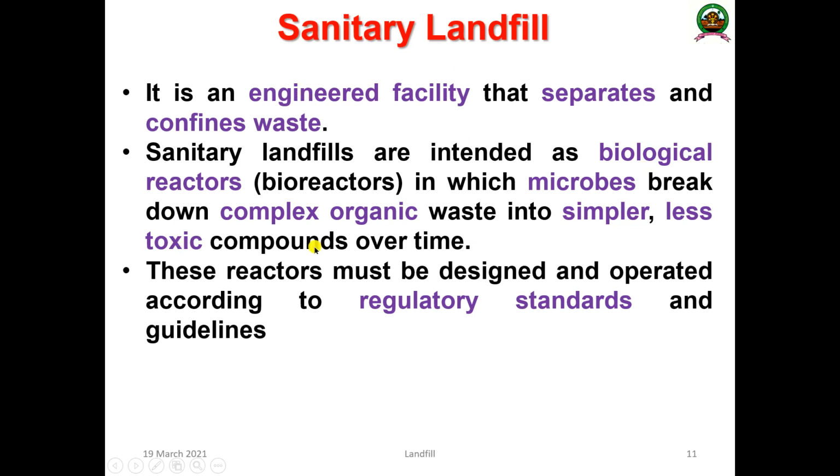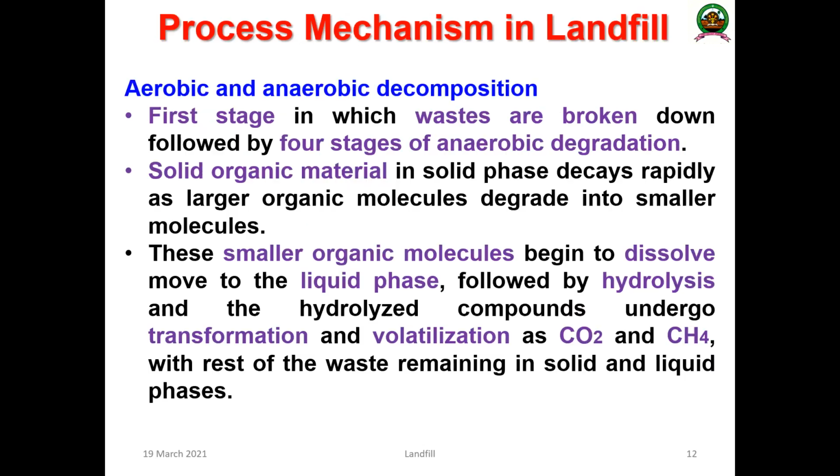This landfill is a biological reactor, that is, the waste materials are kept in a reactor or bioreactor in which microbes are applied, which break down the complex organic molecules into simpler, less toxic components over time. And these reactors must be designed and operated according to regulatory standards and guidelines. So this is very, very important. Nowadays, biotechnology is very important to develop such landfills or bioreactors for processing solid waste.